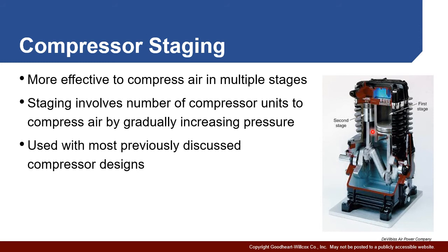This has actually two pistons. The first piston does the initial pressurizing, and the air comes out of this one, goes into this second piston, and then the second one pressurizes it further. If you're ever wondering which is the first stage and which is the second stage, a dead giveaway is the size of the pistons. Right? If you take a look at the first stage, it's a very large piston. The second stage is a very small piston.